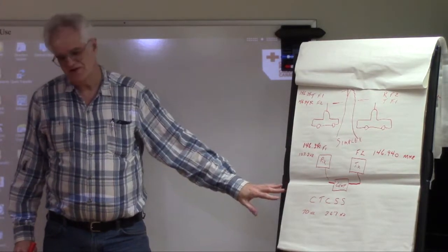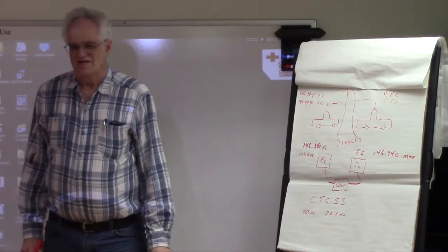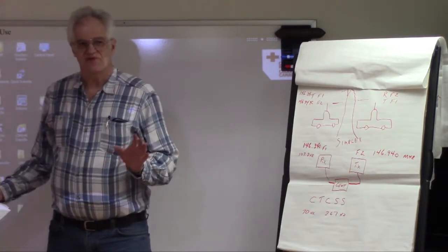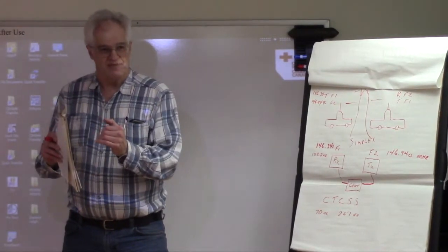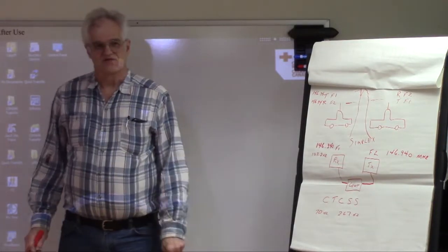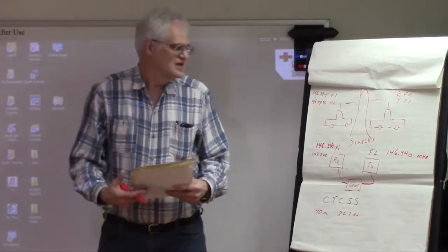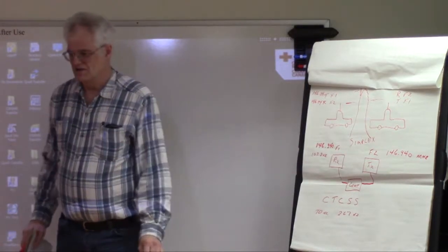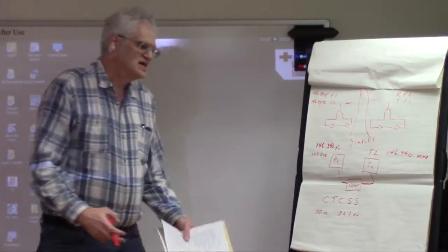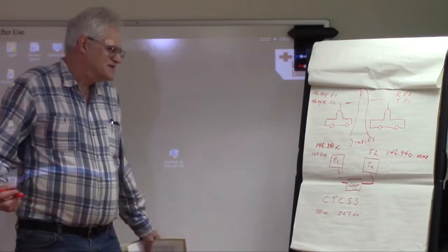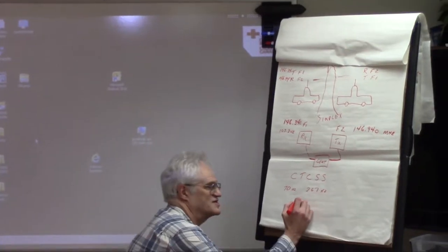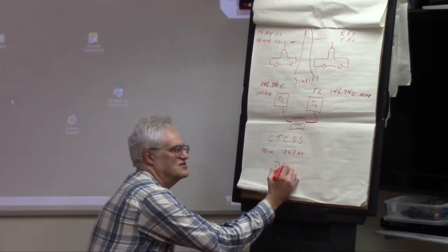One of the purposes they use the tones for is you could actually have two repeaters on the same frequency that could possibly overlap. So if you want to be very selective and say, I only want to use this radio, or I only want to talk to these people, we'll use these set of tones. There's another term which is starting to come. We don't use it around here, but some places they use it just for term of reference.